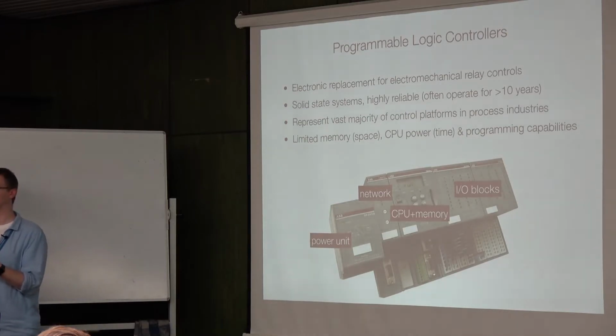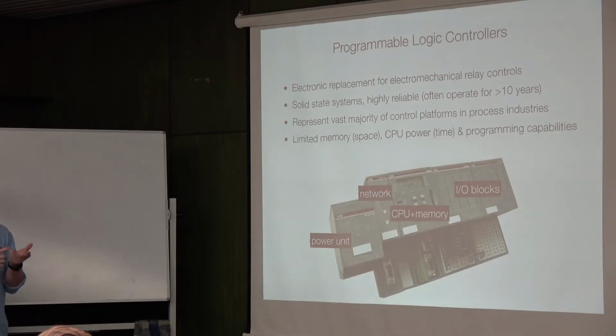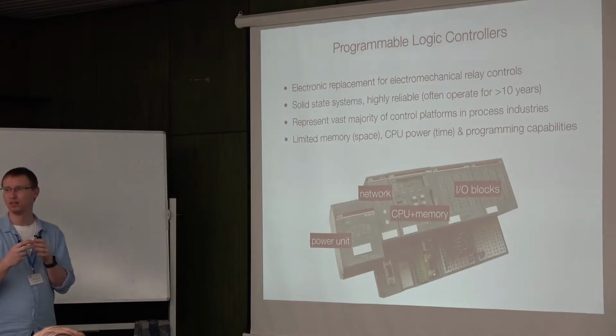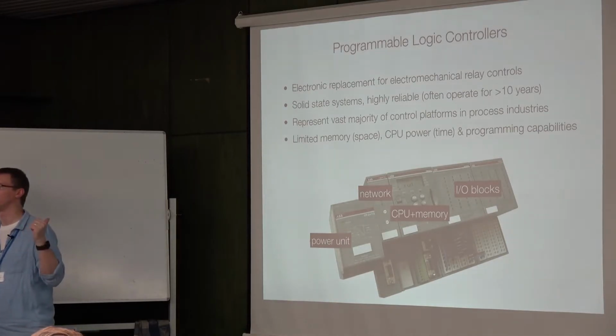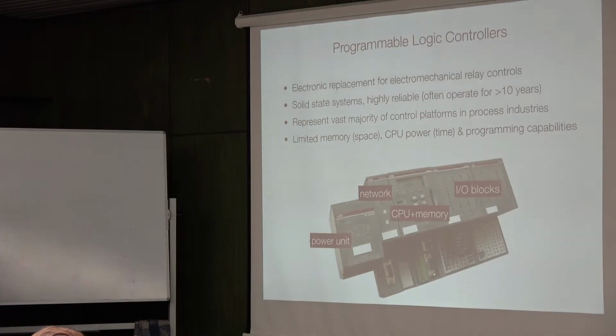We are talking about CPUs which are equivalent to Intel processors from the previous century. And they have programming capabilities which basically means we have to program them using a kind of assembly language. So these are really such severe limitations that you would be lucky enough if you can get LQR running on these controllers, and not MPC or something like that.